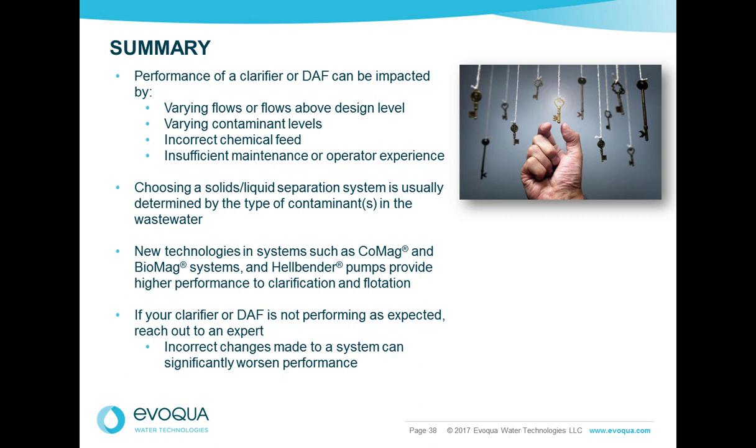Okay, in summary, Alex and I have reviewed a number of guiding principles for and the applications of gravity clarifiers and DAFs. It is clear there are many things that can impact the performance of these systems, which includes varying flow rates and contaminant levels, which was indicated in our survey, inadequate chemical feed for flocculation, and insufficient operator attention. It is also clear that choosing a solid-liquid separation system is very application-specific and driven by the type of contaminants being removed.